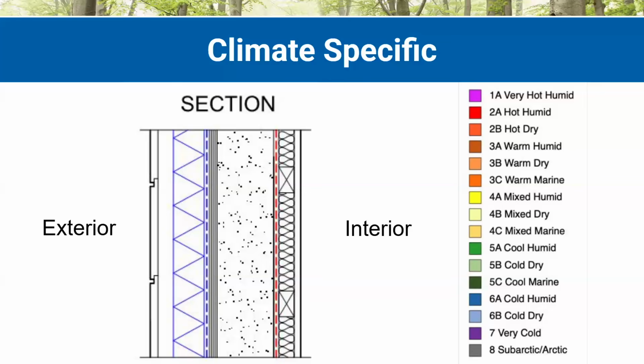We're changing our levels of R value, but in general, we're still shedding the water as number one. We are still air sealing projects regardless of climate zone. We're adjusting our vapor control a little bit, and we're adjusting our R value. But there is still that order of priority. I do want the assembly to dry through diffusion more than I want the assembly to be super insulated.